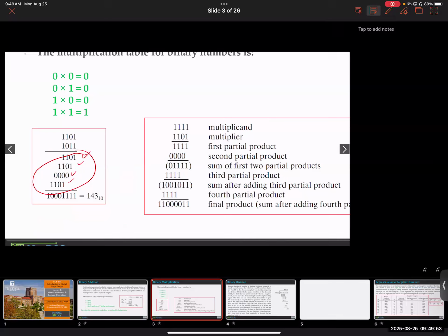I know it might sound a little bit confusing because I'm getting ahead of myself. I just wanted to point you towards a hardware decision that we have to make based on how the math is done. This is how the math is done. You have to add them together. But when I try to add them, I have to manage carry, which can overflow. Okay, I will keep some extra bits for it. I will keep like 4 bits extra.